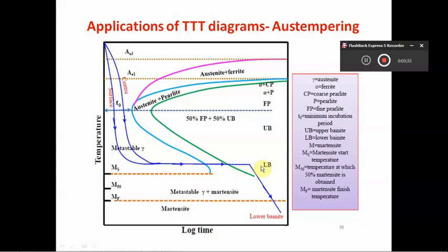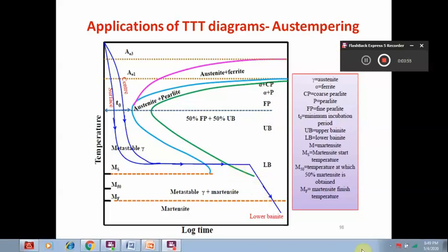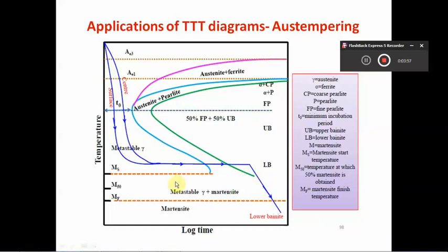However, it has some limitations or disadvantages. The hardness produced is not as high as that produced by martensitic transformation. Since the critical cooling rate has to be exceeded during cooling, the process is applicable only to slightly hardenable steels. Then the holding times are much longer, as it is a very lengthy process to constantly hold the temperature. Hence the process is expensive in nature.